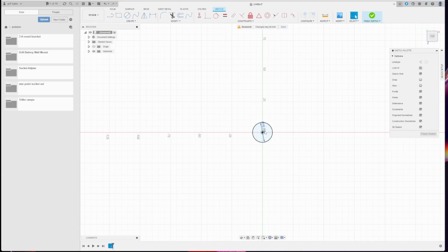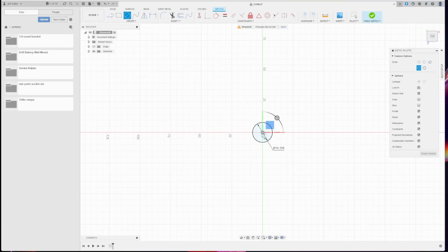So we're going to drop that in, and you can see that it automatically converted that to metric here. Now, we're going to need to create another body here, and I'm just going to grab my circle tool, and some of this I can wing. I can also take my bathroom spout and use my calipers to go across it and measure the diameter, and I get 2.5 inches. So I know I need to be under 2.5 inches, but definitely greater than the 640 thousandths that we designed the part to be. So I'm just going to kind of eyeball it in here with what looks good.